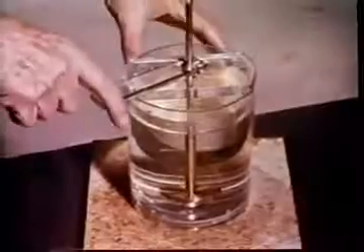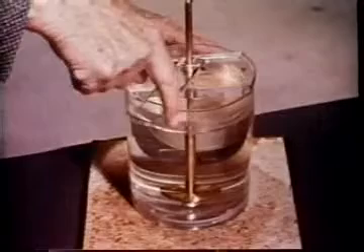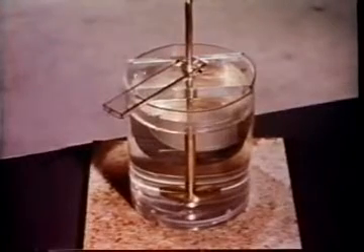Low Reynolds number flows are reversible when the direction of motion of the boundaries which gave rise to the flow is reversed. This may lead to some surprising situations which might almost make one believe that the fluid has a memory of its own. Here are 2 concentric cylinders. The fluid can be moved by turning the inner cylinder with this handle. The annulus between them is filled with glycerine.